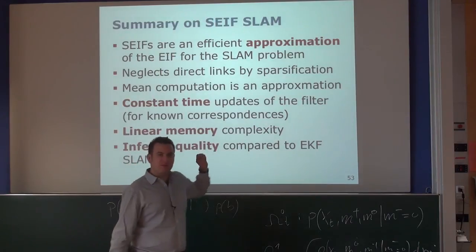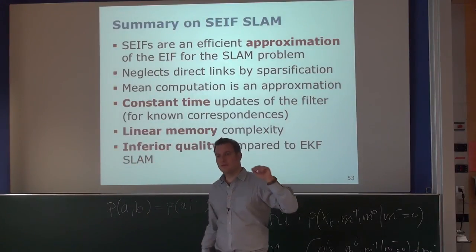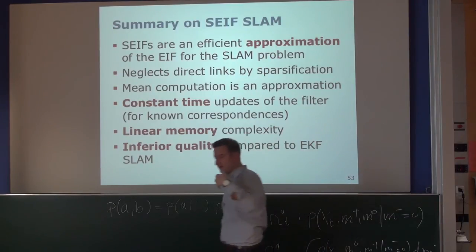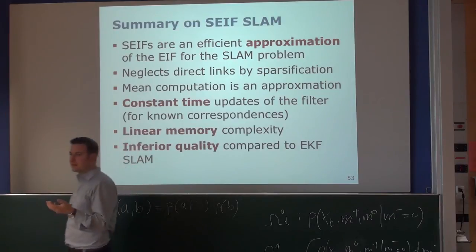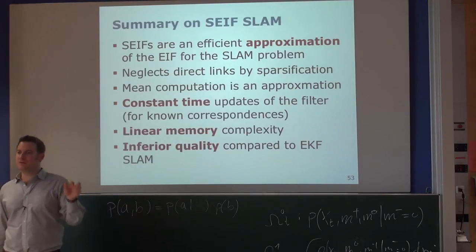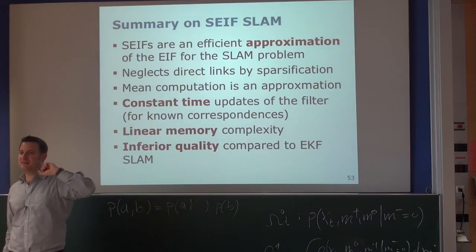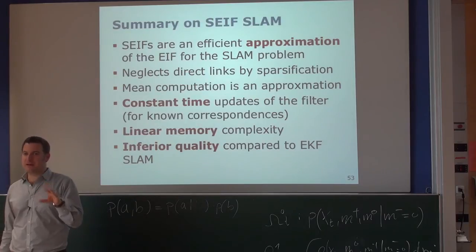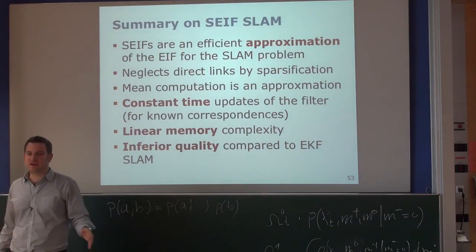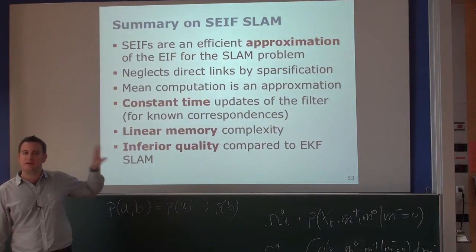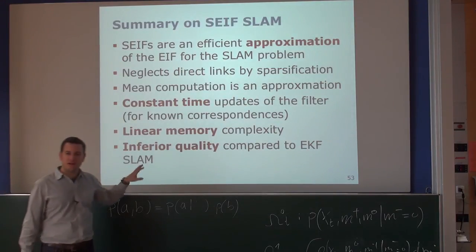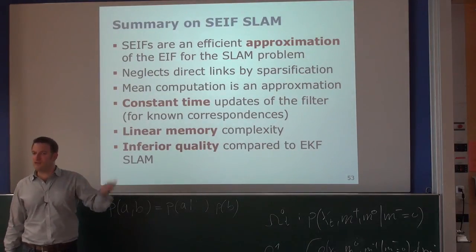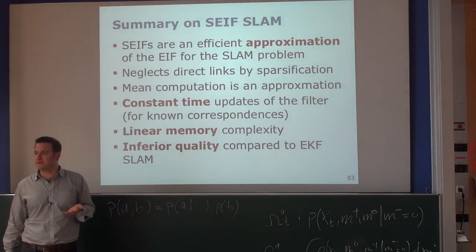The SIFE framework itself is not always directly applicable to other problems. If you have another problem which has a very similar structure to the SLAM problem, that means you have only a small number of dimensions which are updated in the prediction step, and only a small number of variables that are observed by a measurement update because you have, let's say, a sensor with limited range, then you can actually apply it. But it's not as general an estimation technique as the EKF. Or you can do it, but then it loses the great performance that it has. So it's something to keep in mind.